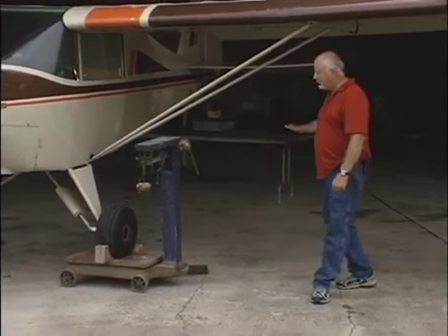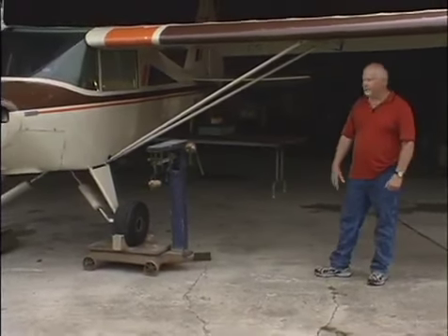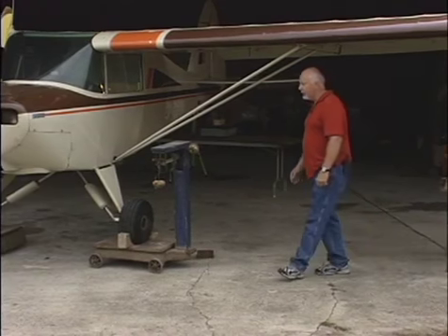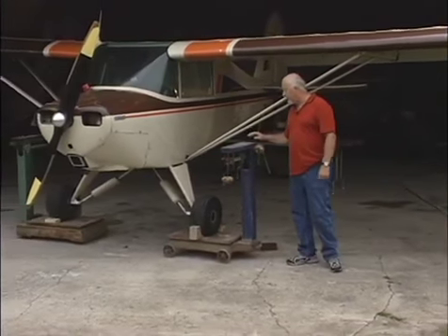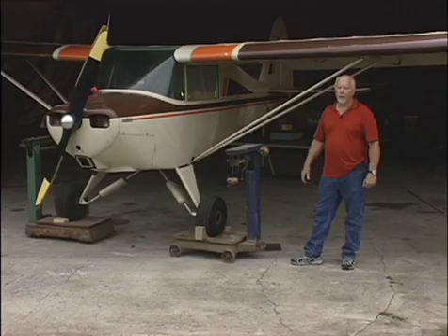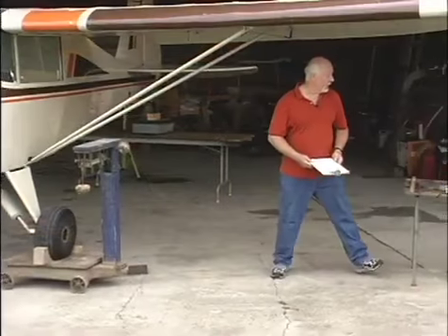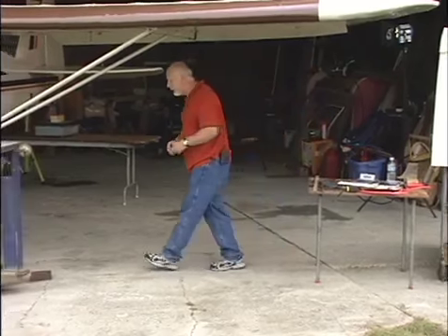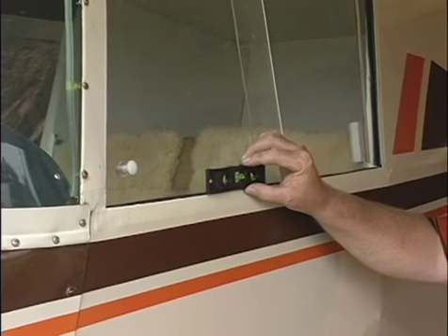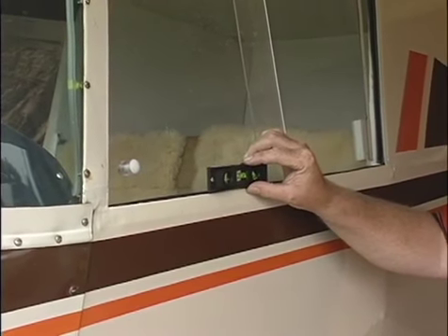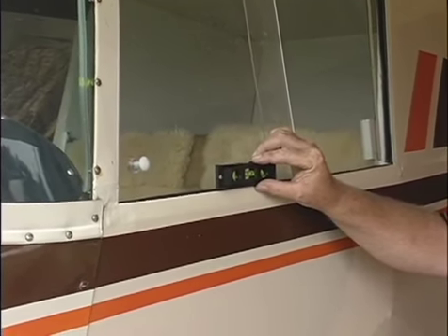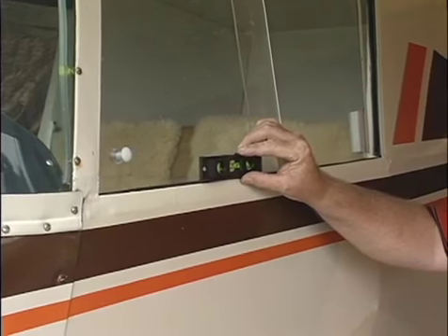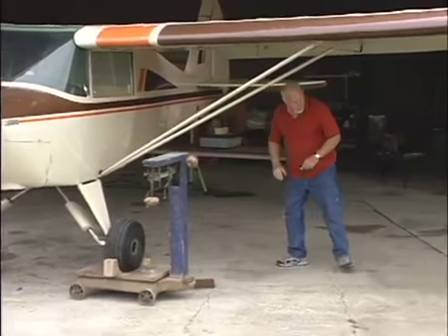The hangar floor is level and it's swept clean. Try and do your aircraft in a hangar when it's not windy. You want to make sure the aircraft is in flying attitude. Now this particular airplane, you lift up the tail and you put a level on here and get it into a level attitude, a flying attitude. So we had to do that.